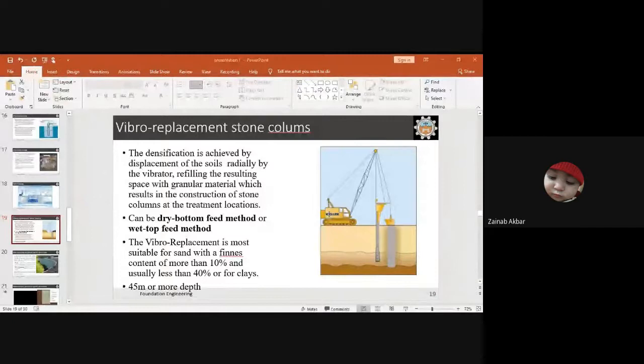In the facing element, we provide precast concrete panels or wire mesh. They hold the soil between the reinforcement layers. Soil reinforcements are typically steel or geosynthetic fibers, like polymeric materials such as rubber, etc. The stability of the wall system is derived from the interaction between the backfill and soil.